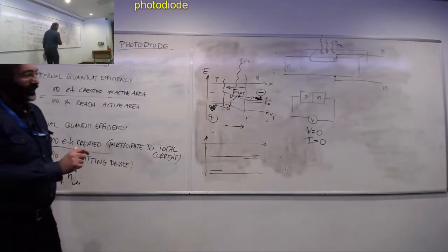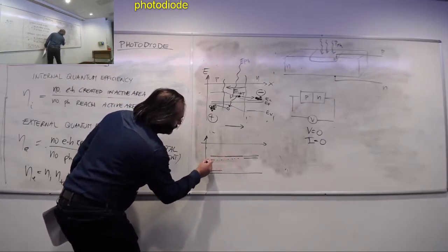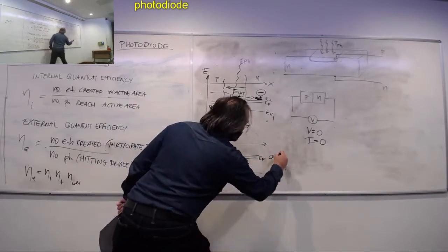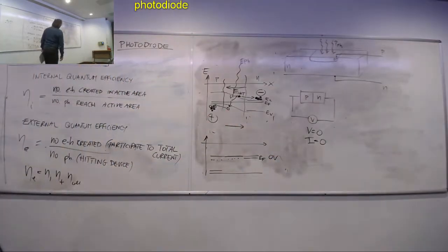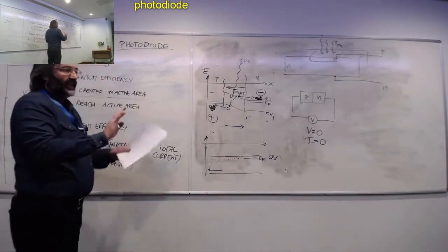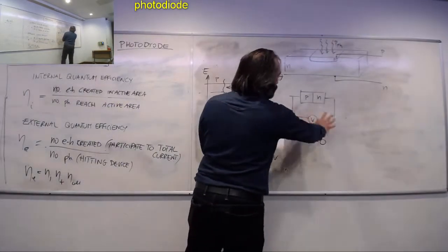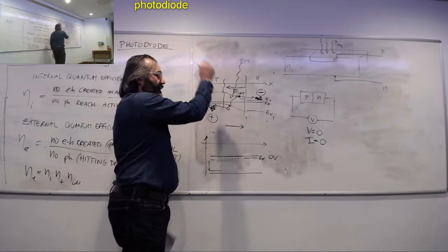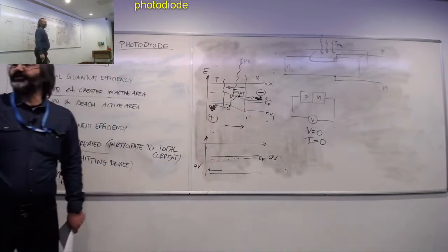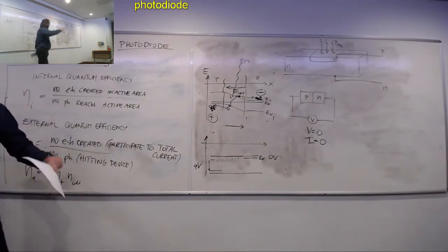The second thing is, this was the Fermi level. This is the Fermi level on the n side, which we assume is at a reference potential. So what is happening here now is that, as I said, I'm doing nothing to the p-n junction in the sense that electrically I'm just measuring. The only thing I'm doing, I'm shining light. What I say is that now there is a potential being generated because there is now a non-leveled Fermi level.